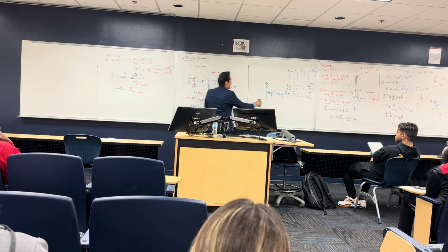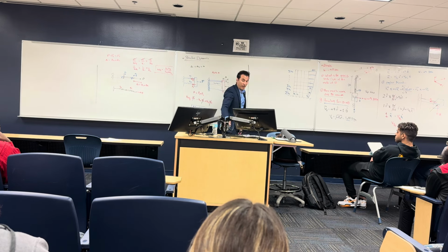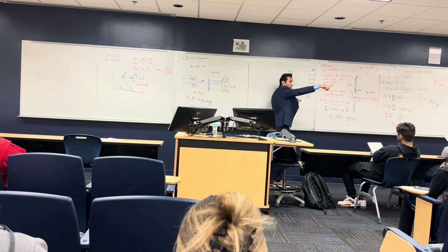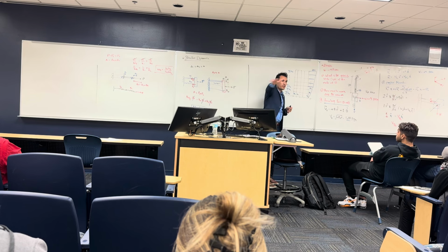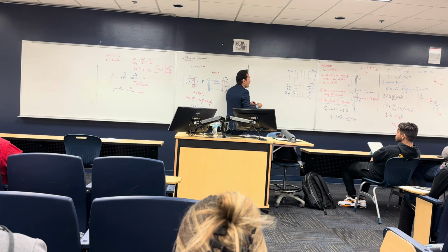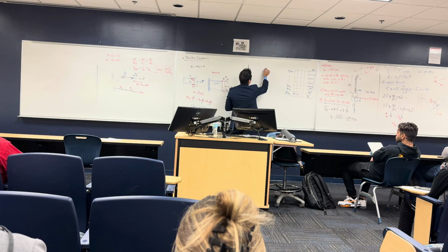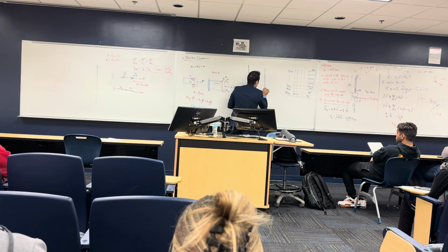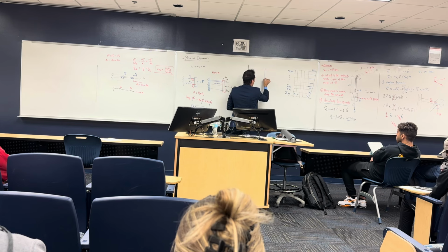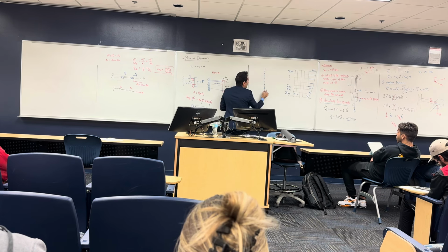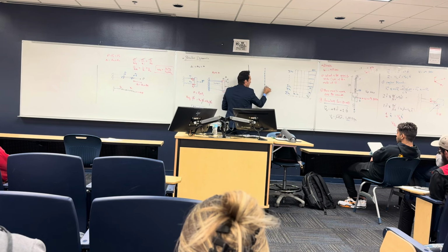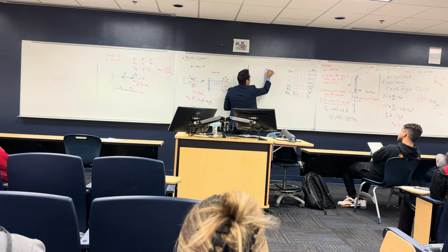Let's go to the second part. What I did right now is lump all the stiffnesses of the columns together. I have a column here and a column here and a column there, and I sum the stiffness of these columns into one big column, something like this. My building starts to be the sum of K for one column and the mass of the slab, then K2, K3, up to the sum of Kn.